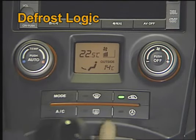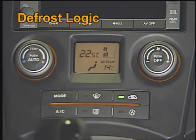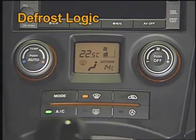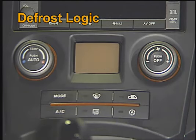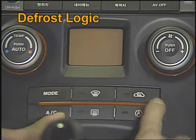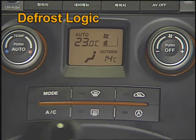Now, let's study about the defrost. That is, how to set the defrost logic and to release. First, press the defrost button to select the flowing mode to the front window. Next, press the aircon button and press the inner air button at least 5 times within 3 seconds. If the button signal is normally inputted, the control panel screen will blink 3 times.